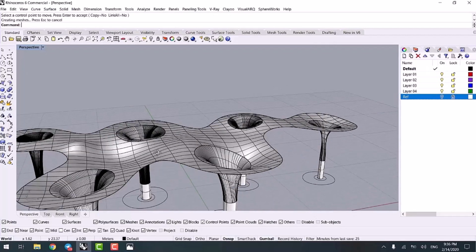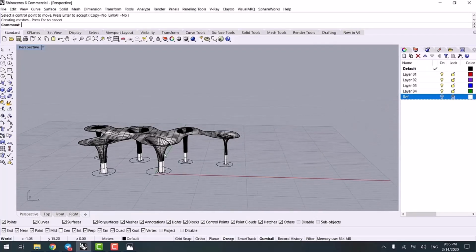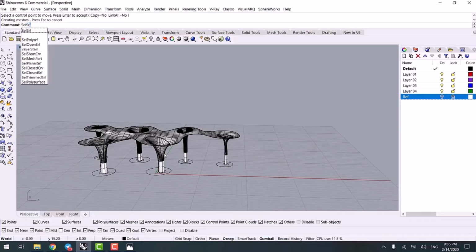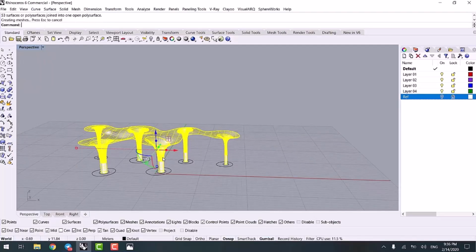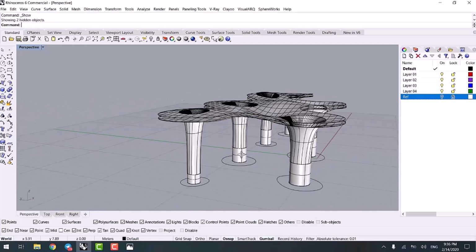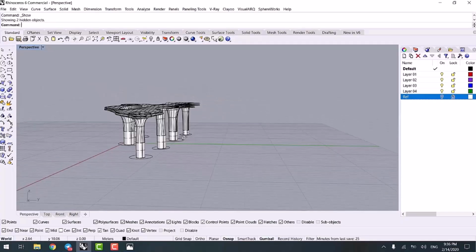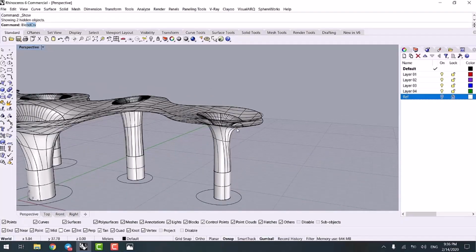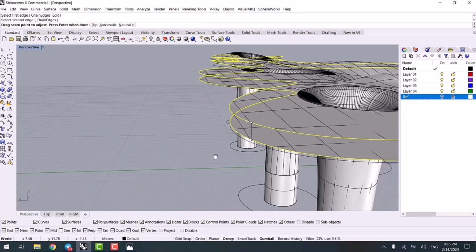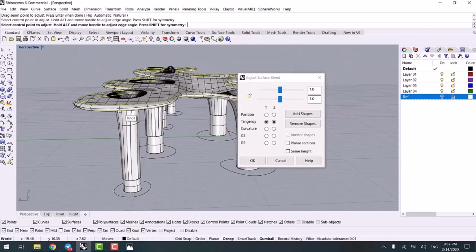You could make all of these changes, and after that select cell surface, Control J, and Control Alt H. So we would have our previous surfaces unhidden. After that, with the use of the blend surface command, we connect these two edges together. Just like this. And then in the end, join them all together.